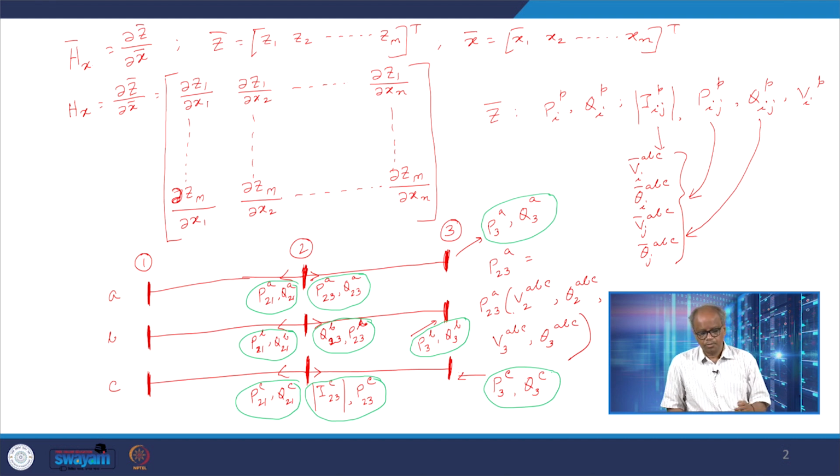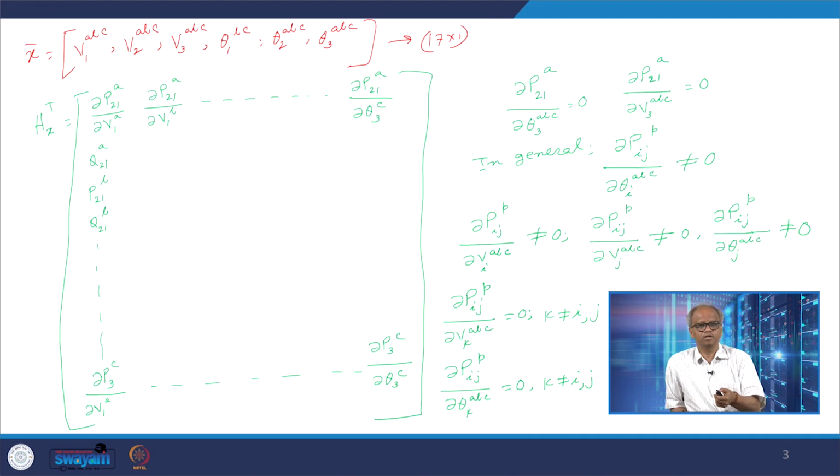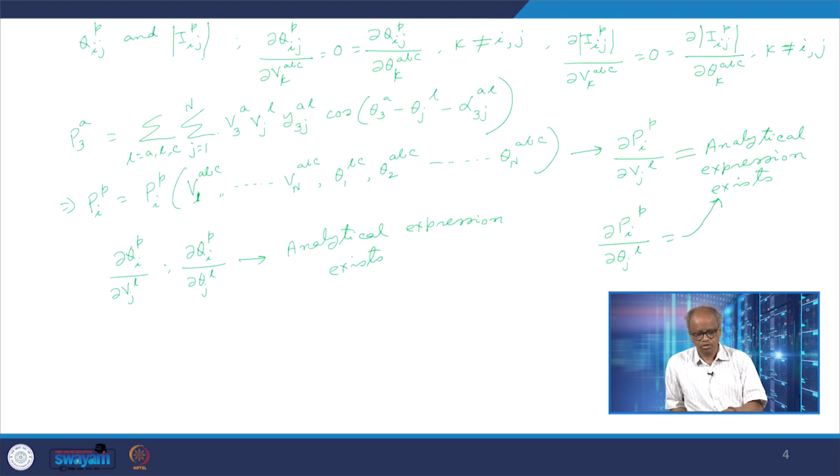But for a large network, we really cannot perceive it visually, because there will be only data. So we have to form this Y bus matrix by our computer code, and following our algorithm the corresponding elements of the Y bus matrix would be either 0 or non-zero, depending upon whether these two buses are directly connected or not.